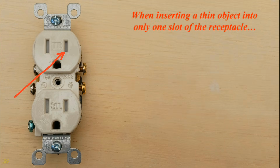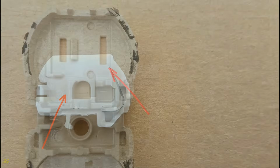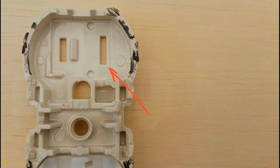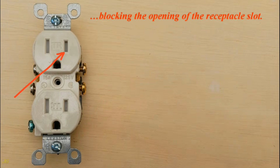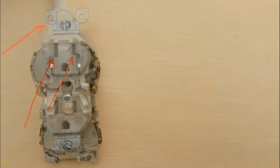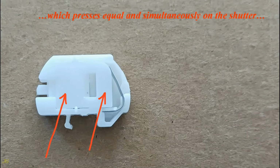When inserting a thin object into only one slot of the receptacle, pressure is exerted on one side of the shutter, causing the other side of the shutter to deflect toward the front of the receptacle in the receptacle base recess. This unbalances the shutter balance mechanism, causing the shutter to remain in the same position, blocking the opening of the receptacle slot.